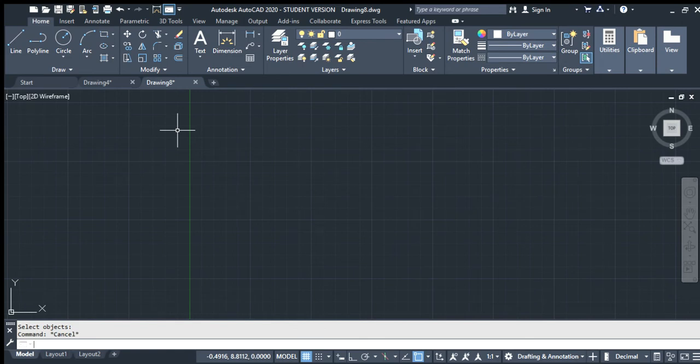So polar coordinates, if you remember from your trig classes, let's go ahead and hit L for line. 1, 8 is my initial point. Trig goes over polar coordinates going off of the x-axis. So if this is my x-axis, then this is basically a vector. So I'm going a magnitude of 1 in the 0 direction as my first point. So 0 direction would be 0 degrees on the x-axis. So 90 degrees would be on my y-axis, negative, or 270 would be -90, so negative y-axis.